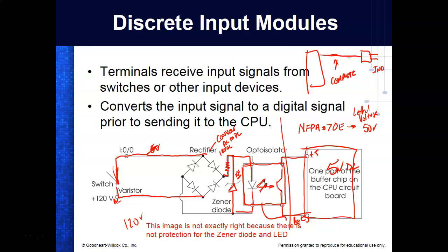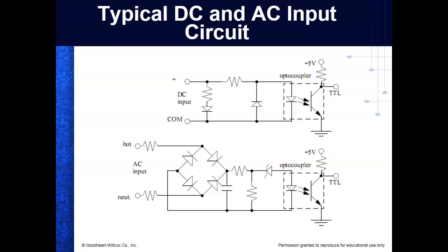So standard, when PLCs use DC, what we use is 24 volts, which is half of the control voltage. So now the PLC is safe, and then we have relays and stuff like that. So 24 volts now. The 500s actually even use 24 volts. So that's pretty standard in PLCs now, newer PLCs.